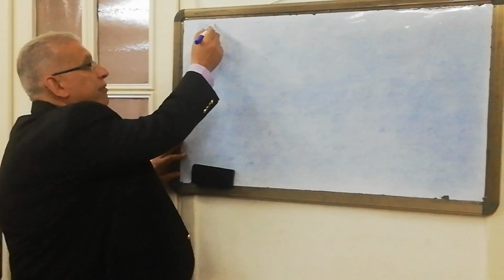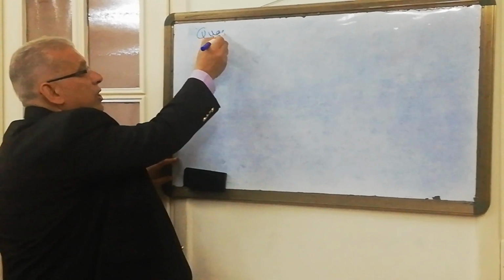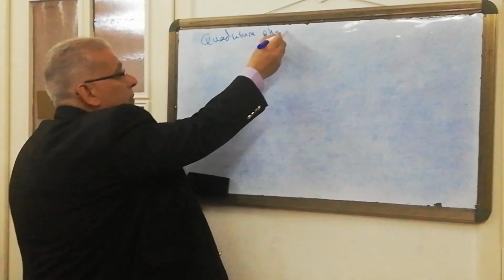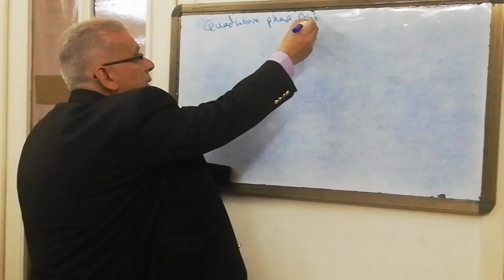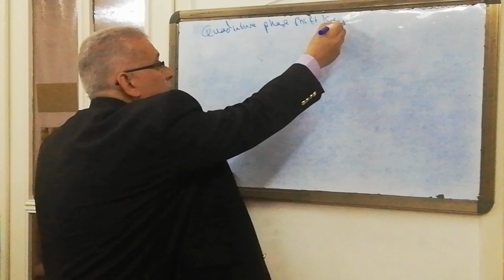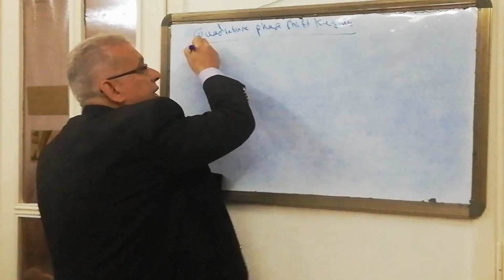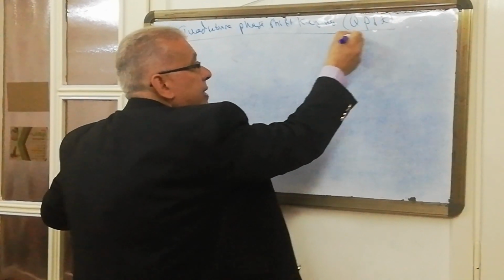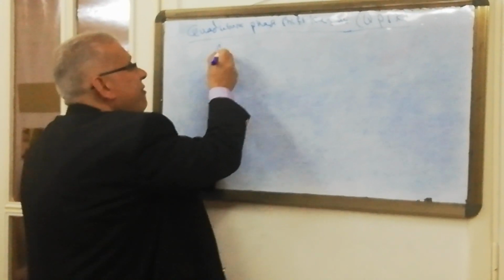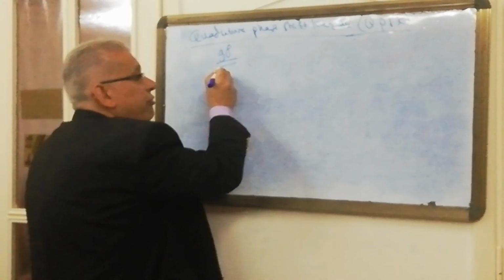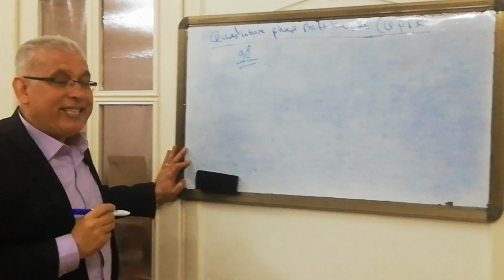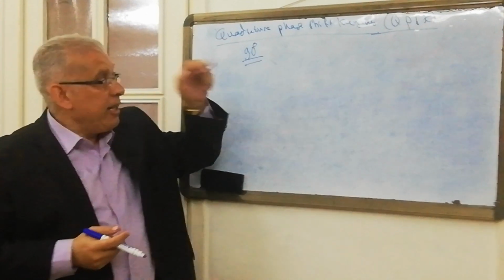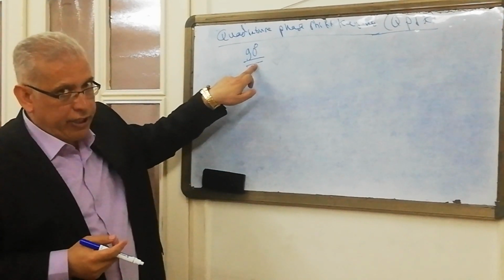Bismillahirrahmanirrahim. Welcome back. Today I'm going to present the fourth type of band pass modulation and demodulation technique, called quadrature phase shift keying. We're talking about four angles, or four shift keying. In this case, we have a 90-degree phase shift instead of the 180-degree phase shift we used in the phase shift keying in the previous lecture. Here we are talking about a 90-degree phase shift.